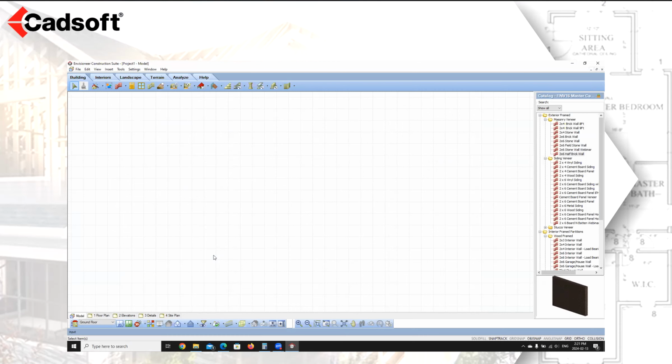Now, just a quick note here, any element in your drawing will be saved as well. So unless you want these elements to appear in all of your new projects, you should delete the elements from your drawing. So if you've opened up a drawing and you've started to create a template from that, any elements that you have inserted will also be a part of that template. So if you don't want that to happen, just make sure you delete everything out, so that way you have a clean, empty template.